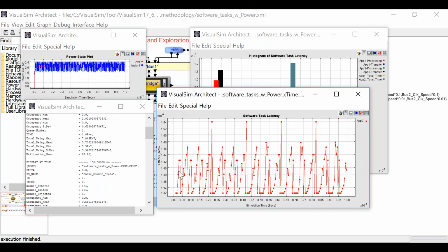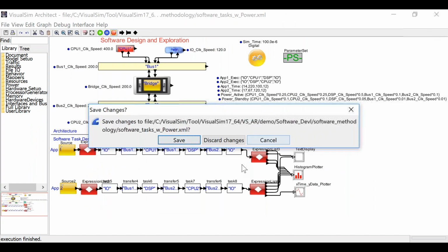then that caused a huge impact on my latency, because what was happening was the processors were getting data in at a much faster rate in the 400 megahertz version, and they were actually queuing it up at the processors. So that's one of the reasons why, with this particular architecture, even though I was going at a faster speed, because the processor was taking longer, it was starting to queue up there, and as a result of that, the latency was going up, or the peak latency was about the same.